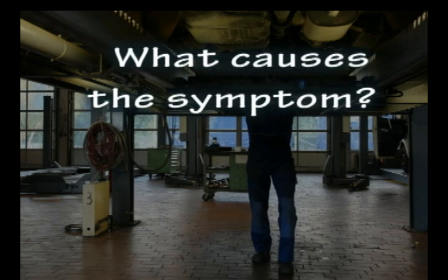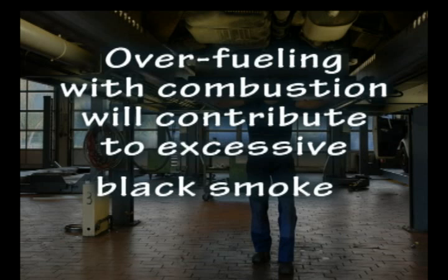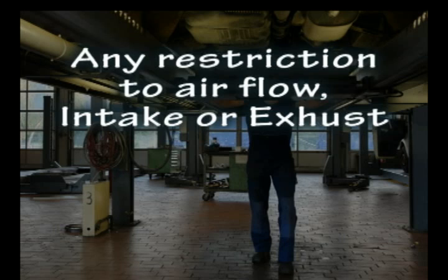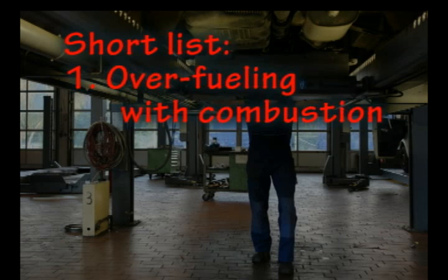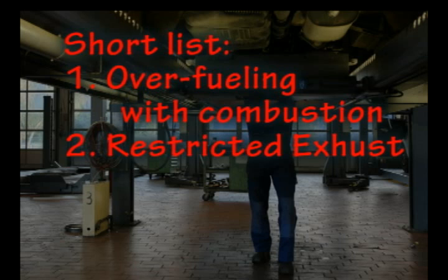It is of utmost importance to consider what conditions are responsible for causing such a symptom. As with any diesel, overfueling with combustion is a major contributor to excessive black smoke. This would be considered a rich condition on a gas-operated vehicle. In addition, any restriction to airflow, whether intake or exhaust, will result in the same thing, as fuel delivery far exceeds the air concentration for proper combustion. So, on our short list, we need to consider overfueling with combustion, restricted exhaust, or restricted intake.